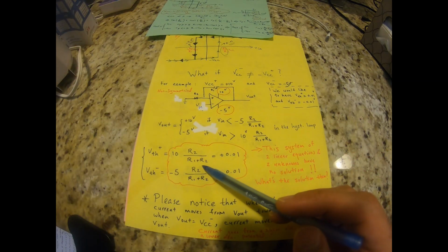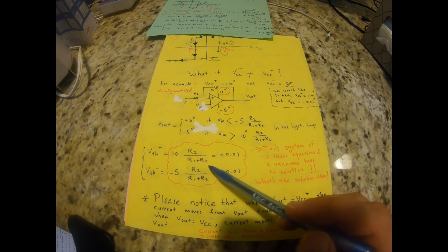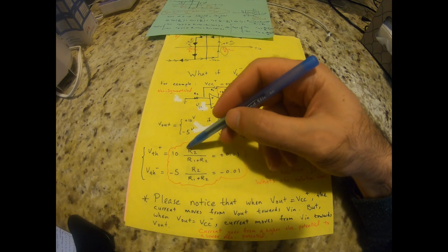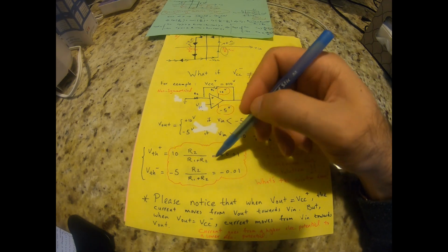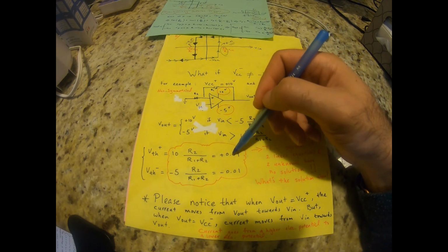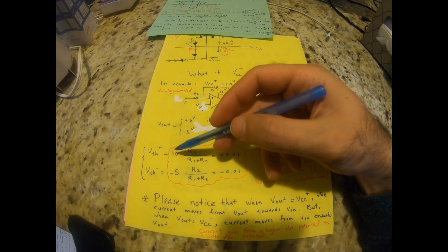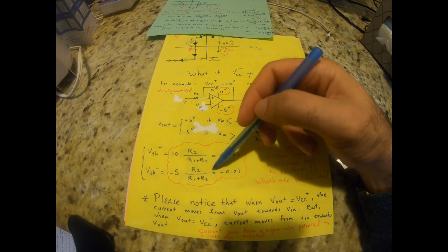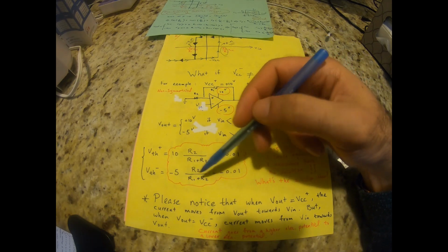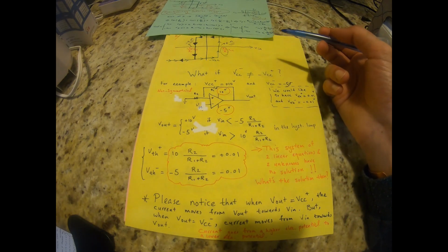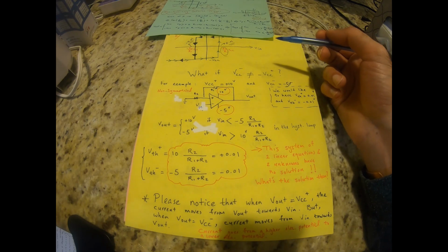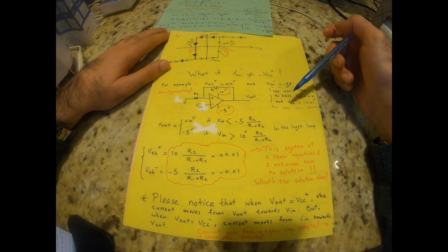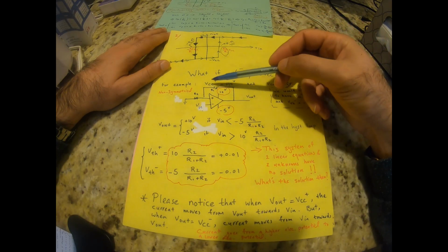But this system of linear equations has no solution, because on one hand, this term has to be equal to 0.01 divided by 10, and based on the second equation, the same term has to be equal to 0.01 divided by 5. That's not possible. So it's not possible to satisfy this requirement with only two resistors.